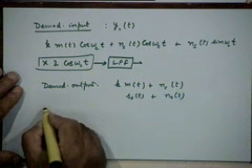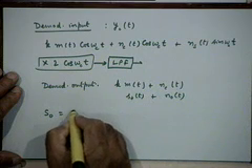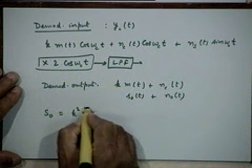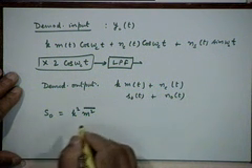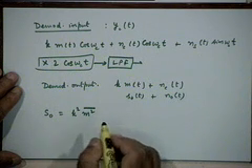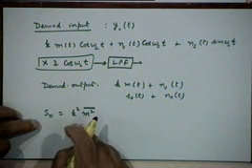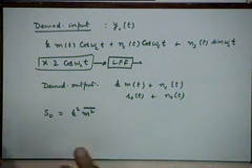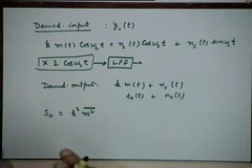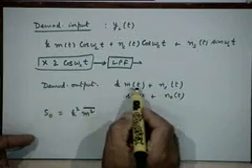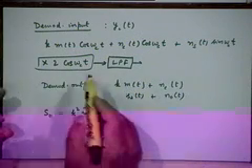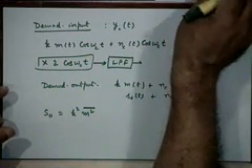So your output power is k squared m squared bar in this case. Now this is not what is given to be 1 microwatt. One has to be a little careful there. What is given to be 1 microwatt is the input power at the receiver, the signal power that is incident to the receiver. What is the signal which is incident to the receiver? It is not k m(t), it is k m(t) cosine omega_c t.